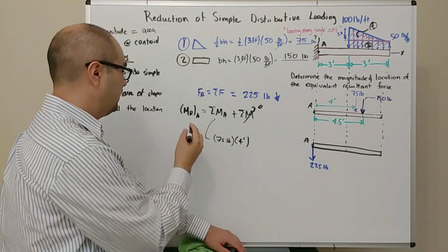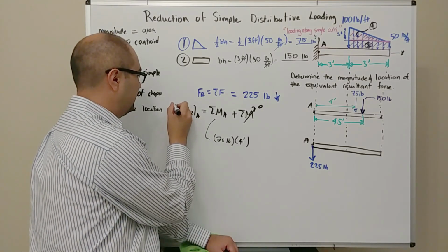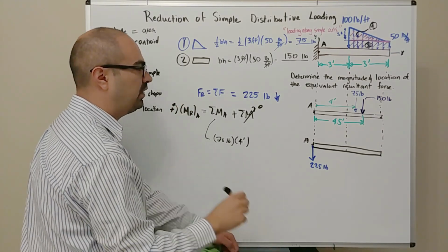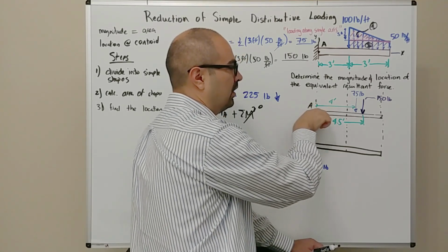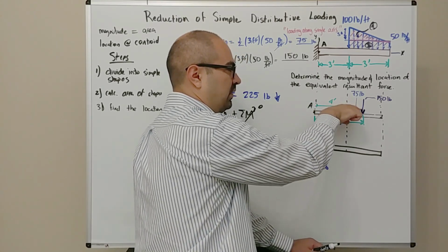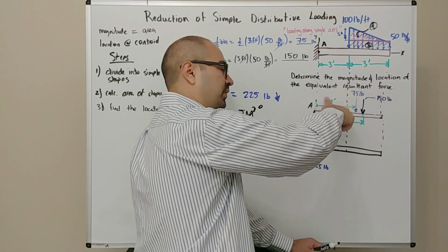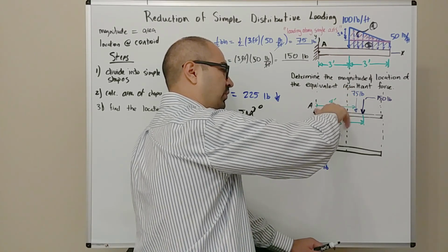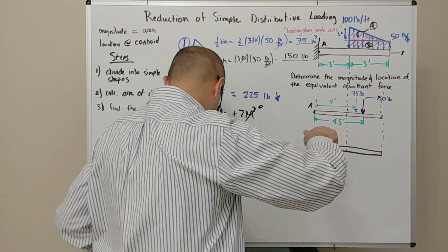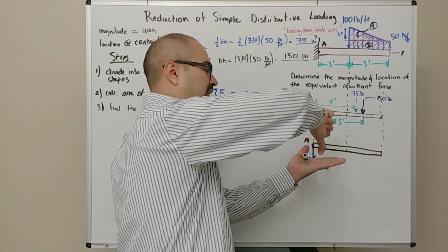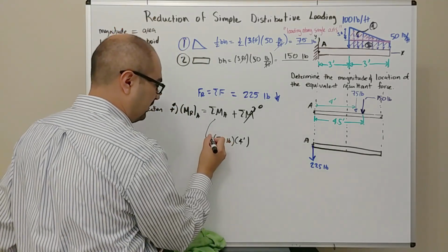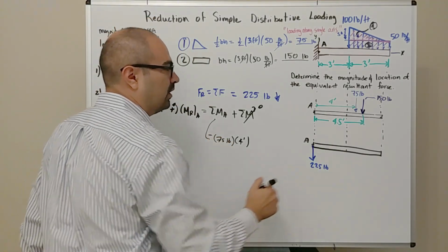and as we're summing the moments, remember we always say if it's counterclockwise, it's positive. In this case, if I'm at point A, we put our right hand there, I point to the force, the 75 curls down, so that means it curls clockwise. Or if you're doing this on a sheet of paper, this would be down, that's a negative moment, so this is negative right here.